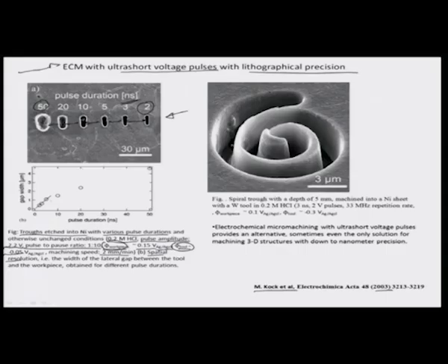So, at about 2 nanoseconds resolution, the gap is close to 25 microns, whereas if you look between 50 and 20 nanosecond resolution, the gap has now closed to almost half that value, probably 10 to 15 microns. So, they do find that there is a resolution aspect in printing while talking about different pulses, and the shorter the pulse duration, the better control the process has, which is what they are illustrating here.